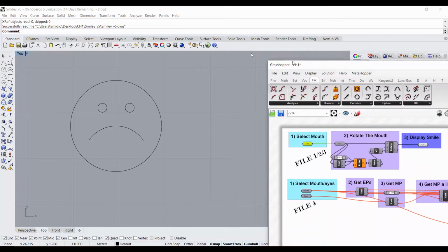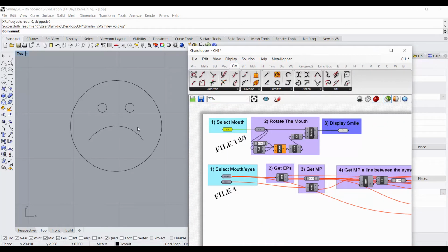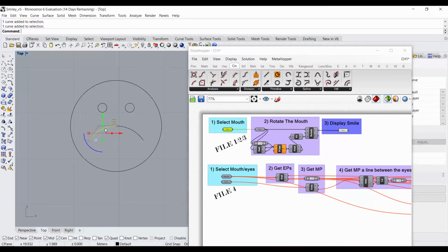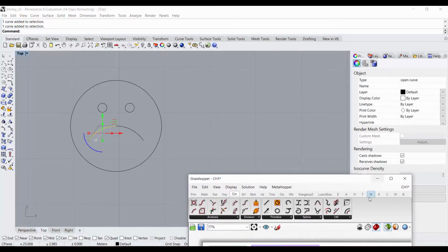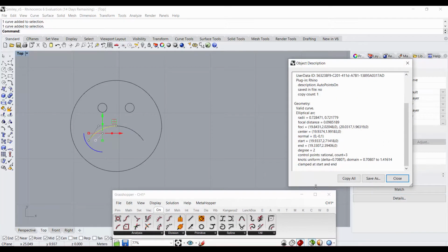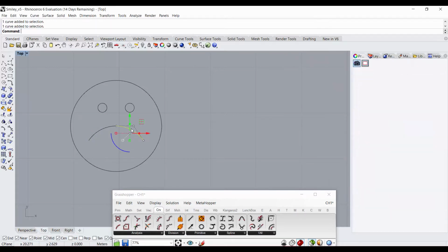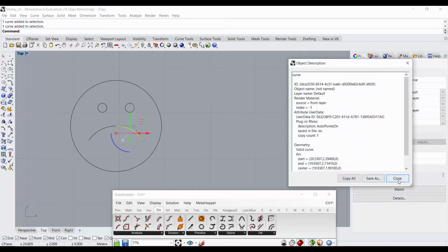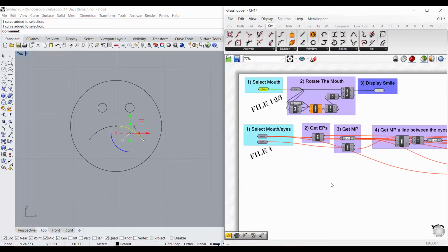Let's see if we could just kind of justify using this first one, which said the mouth was a curve. Uh-oh. Now the mouth looks like two things. It's represented by two things. And those of you in the AEC industry will know this happens a lot. This is a very typical thing. This is an elliptical arc now, and it looks like it's two arcs. So, again, to us, file 1, 2, and 3 looked exactly like this pretty much, other than some small rotation issues. But data-wise,